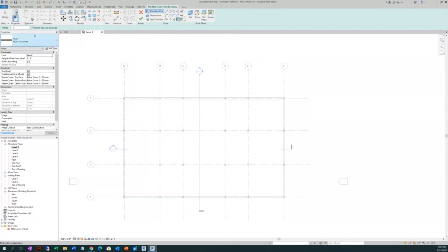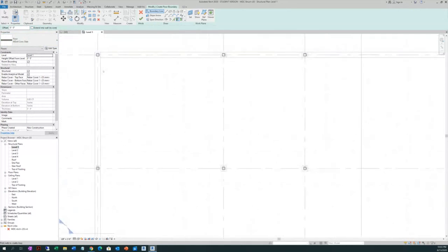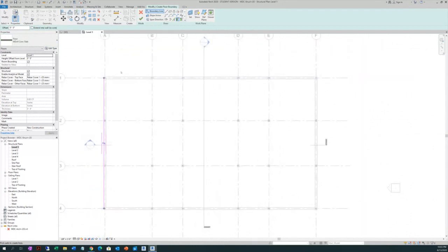Okay. Then you see here on the option bar, offset 0, extend into the wall core. No, I want you to uncheck that. Uncheck extend into the wall core. Then you select this part here on the vertical on your left side, then the horizontal north part, see, have a flip arrow, then the right part, then the bottom part there.